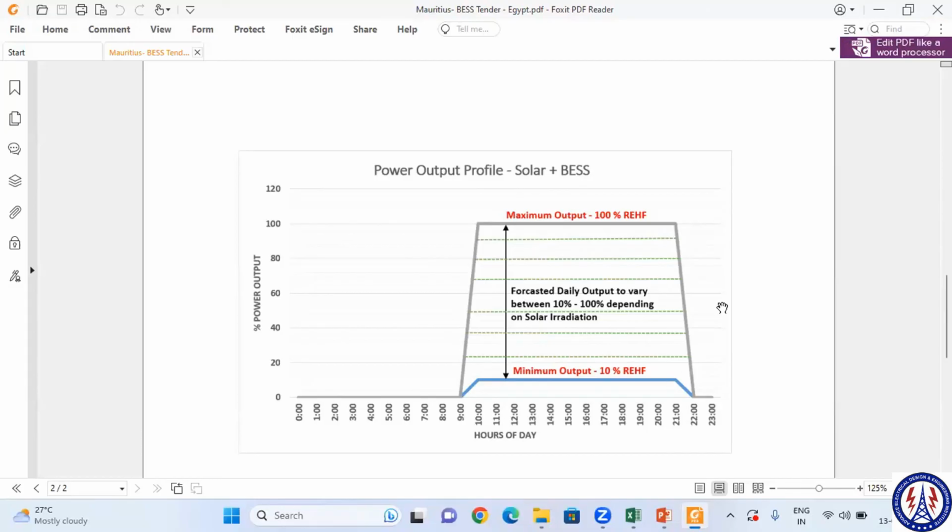Even our plant is bigger, like the 32 megawatt solar plant we estimated. In your scenario, because the DC side is only 12 megawatt and AC side is 10, you need to define how much duration, how much energy you need to store in the battery. The first thing: let's say 12 megawatt is on the ground, and how much are they okay to export, or will every single unit generated from the solar be stored in the battery? What is the scenario?